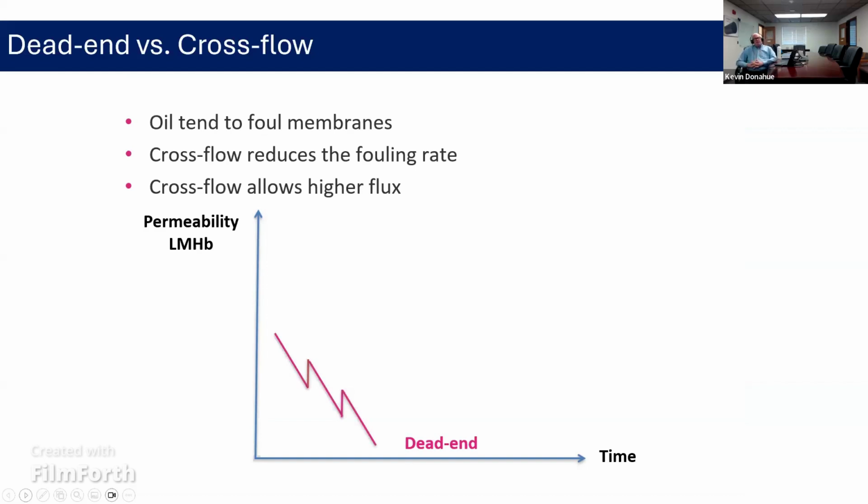As I mentioned before, with cross flow, you're able to run for a longer period of time and with a higher permeate rate compared to the dead end mode. I would say dead end mode is typically used in cases where there's virtually no solids, like I mentioned earlier, potable water. We have some customers that put the membranes on spring water, it's already very, very clean.